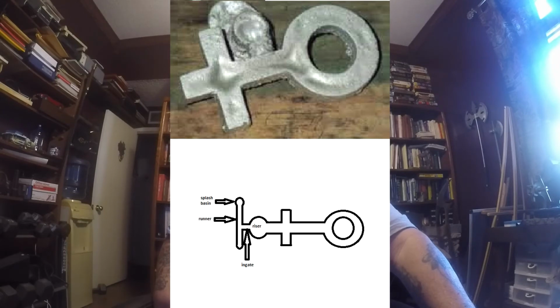And usually the very first surface that solidifies becomes the strongest and thickest at the time that everything's solidifying, and normally that would stay nice and flat. But this was so bad that the metal was too hot, and everything started to pull away as things solidified.